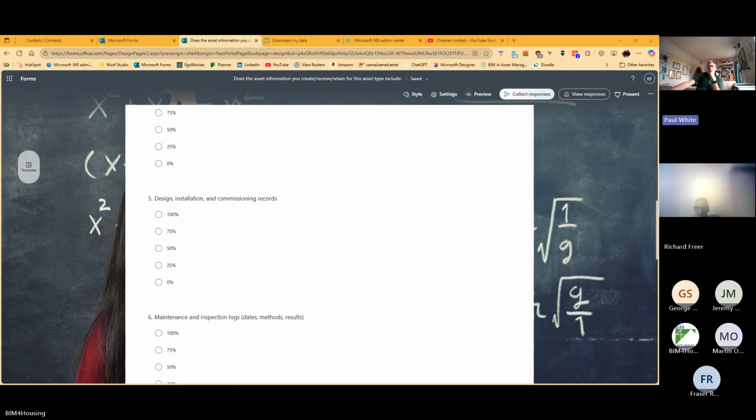But what I see regularly is areas where they've put in just normal fusible link fire dampers, and they've got, as a for instance, phased evacuation. Which means that somebody's either made the wrong decision, but you've got no reference to the actual design decision. It's just we're having these, install them and commission them.